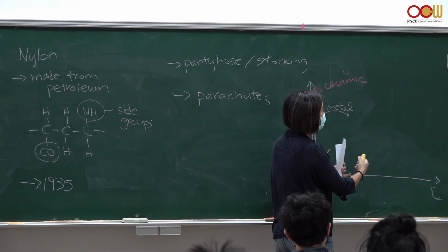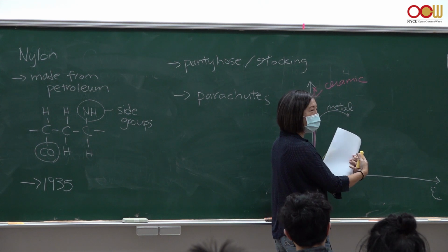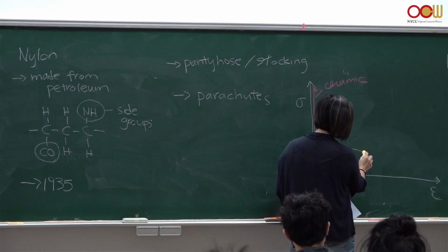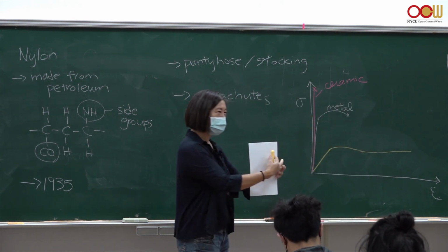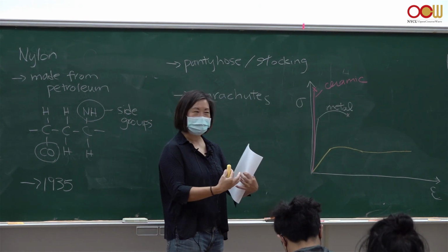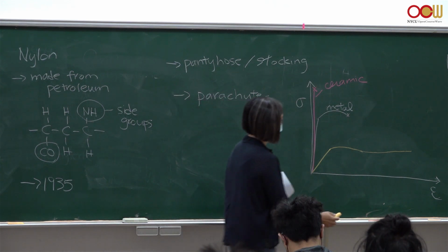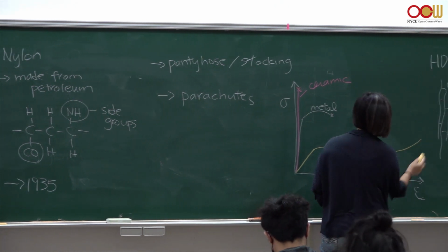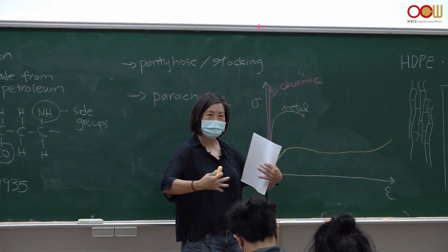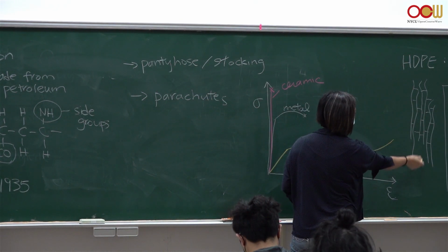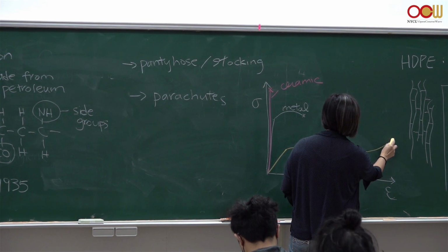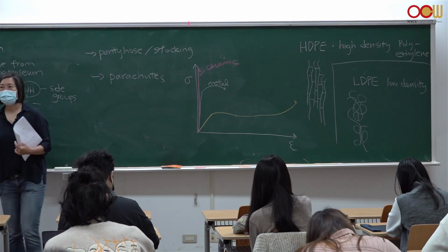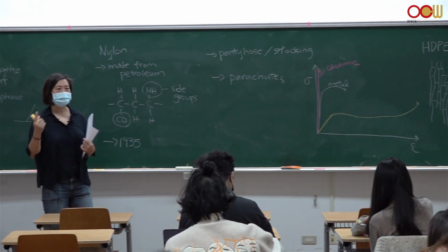And then after you stretch the bonds, you'll start to break some of the secondary bonds. So it's very easy to break, right? It doesn't require much, because you could stretch those depending on the polymer that you made. You could stretch it out quite far. At the very end, you'll actually start to go up, because now you're lining up your chains, and eventually you will be breaking covalent bonds. So the amount of force you'll need at the very end actually goes up.